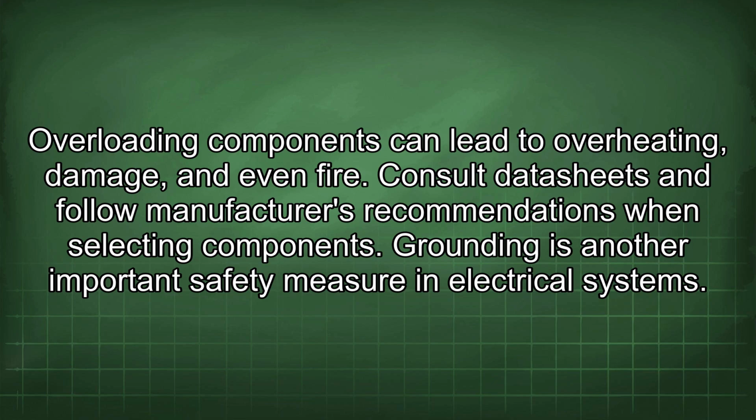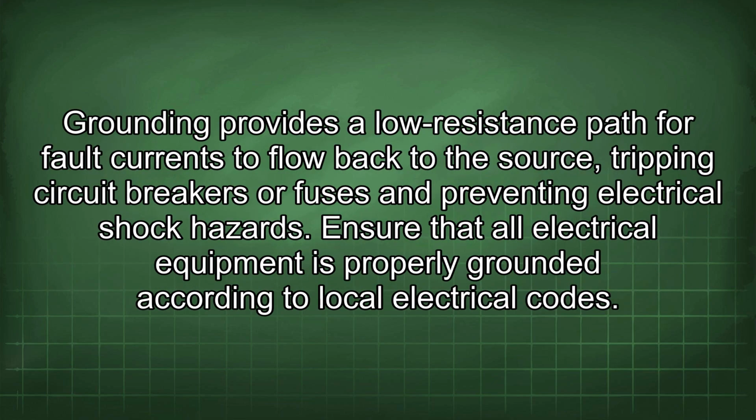Grounding is another important safety measure in electrical systems. Grounding provides a low-resistance path for fault currents to flow back to the source, tripping circuit breakers or fuses and preventing electrical shock hazards. Ensure that all electrical equipment is properly grounded according to local electrical codes.